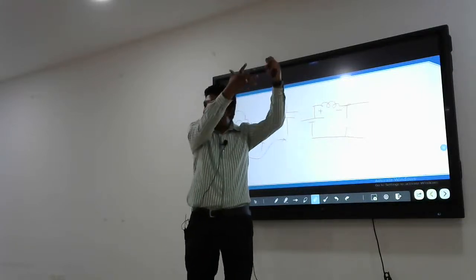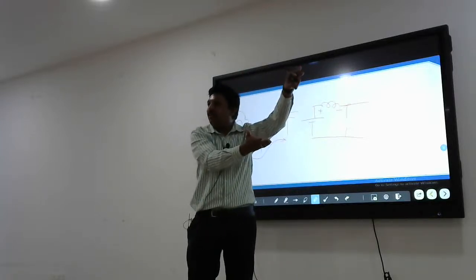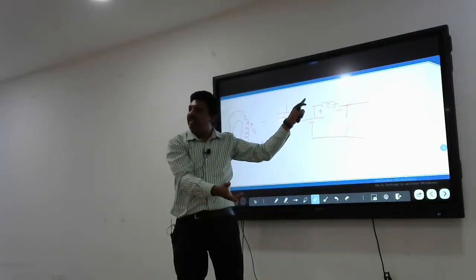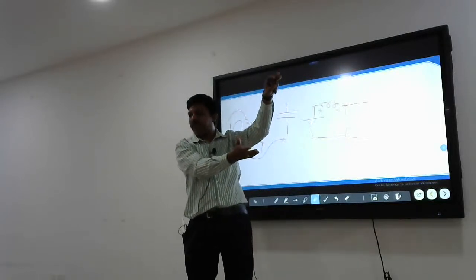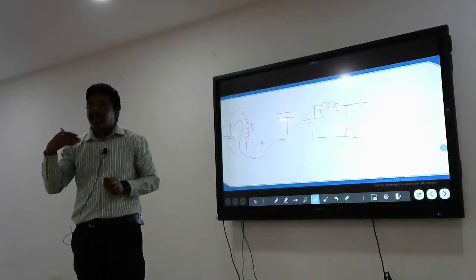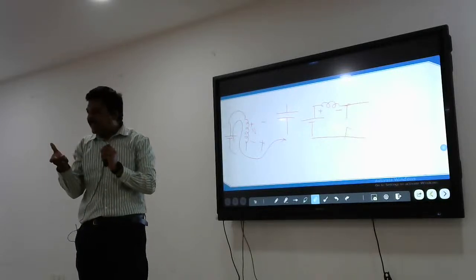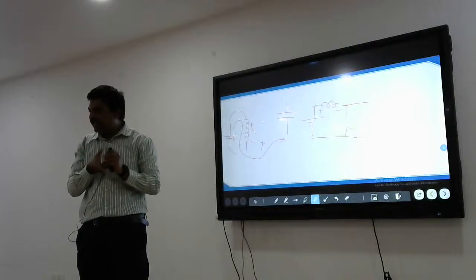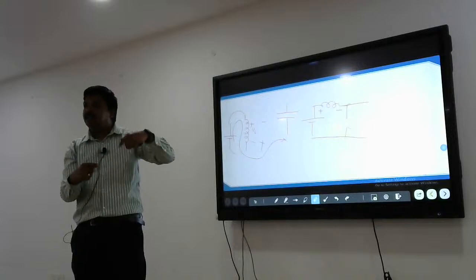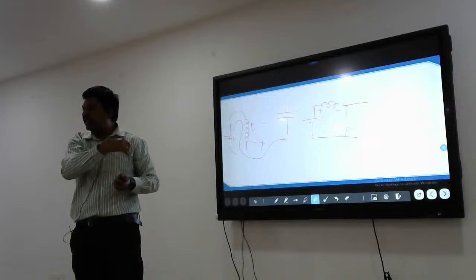And then we are connecting it to the capacitor. The capacitor is a stiff voltage source, so the voltage across the capacitor is VL plus VIN. VL is equal to VDC, so VDC plus VDC is 2 VDC, for example, at 50% duty ratio. Are you clear? When you want to develop any high gain converter, during charging the voltage is applied, and you see that during discharging it should aid the DC source. You place the physical connection of the inductor such that it aids the DC source.